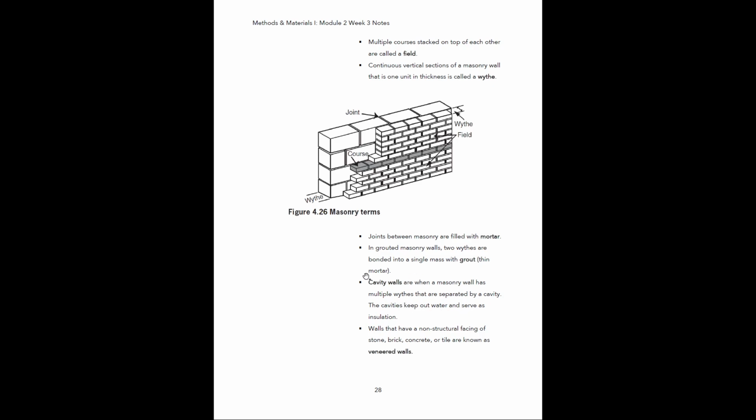Okay, so in the last module we talked about air spaces between wall cavities a little bit. Just the dead air between 2 layers of a wall is going to act as a natural insulator. There are code requirements for how big the airspace should be. The distance between these 2 withes is about 2 inches, and that's going to vary depending on a bunch of different factors.